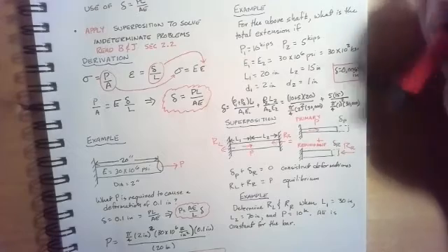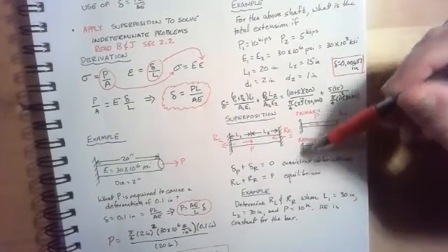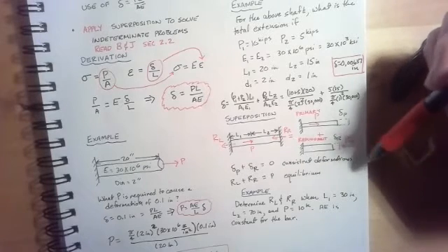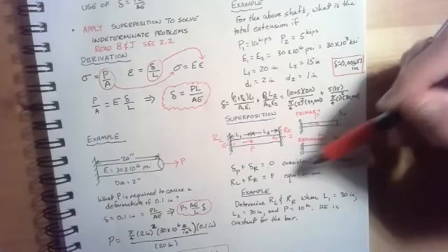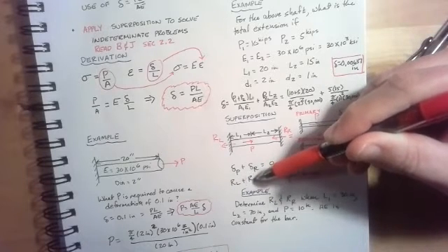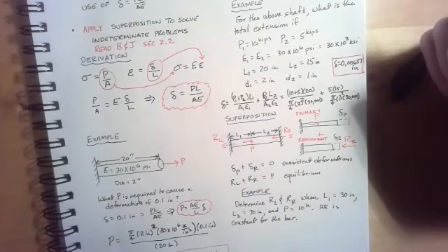So what we would have is delta P plus delta R equals 0. Delta P is a rightward deflection. Delta R is a leftward deflection. So when we add them, they add to 0. And then the right reaction plus the left reaction has to be equal to P for static equilibrium.